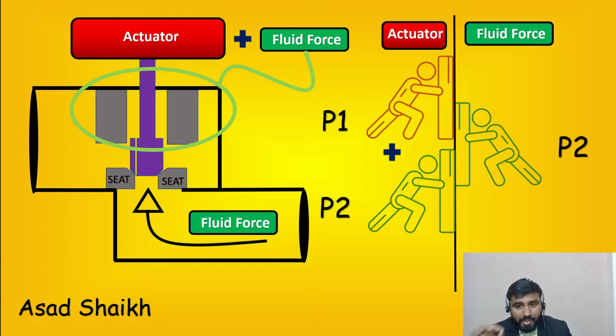Now my first point here is, if you read the ANSI FCI standard, the first thing you will notice is that the leakage class mentioned as class 6, with bubble shutoff and only a few bubbles visible, I don't want to go in depth, but I want to make you aware that it is only at standard conditions, at a very small pressure drop, temperature, fluid, etc. What I mean is, if your application requires extremely tight shutoff, do not use a control valve.